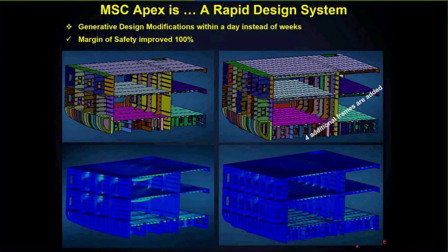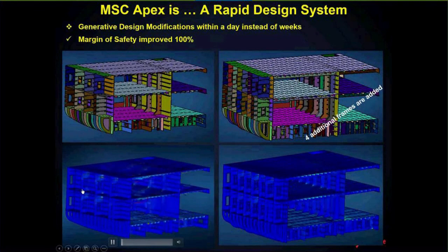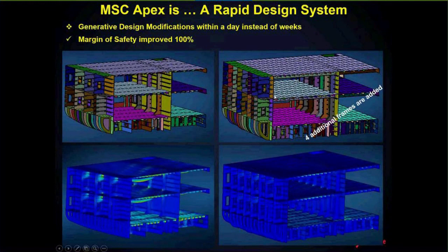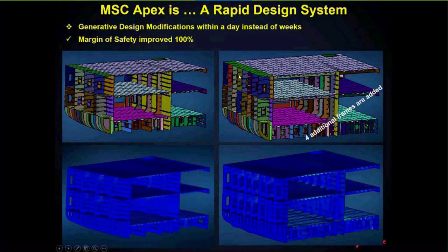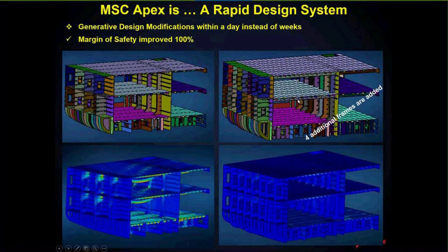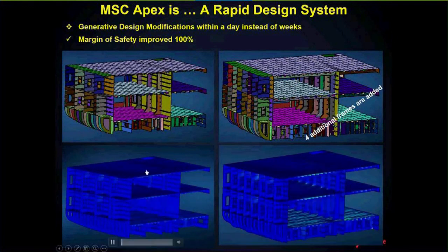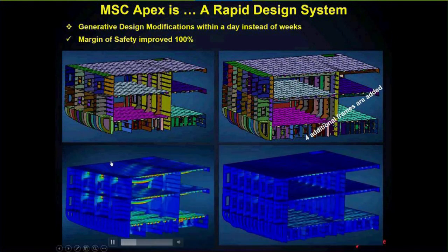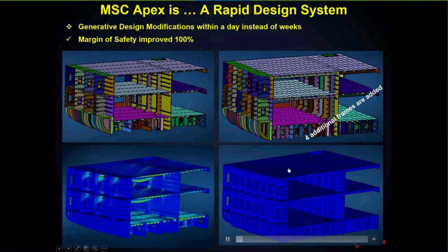Here is a model that I ran, and while we are waiting for the run to go through, this is the original model with 3 frames, right? And now in the modified design, in fact, I've added many more frames here, maybe 4 more added to that one. And as you can see here, with the given identical conditions of the result exploration, now we had kind of caving of this floor much more than what you see here.